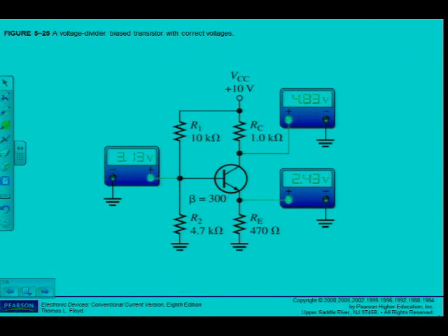All right, now as soon as you've calculated these values and you go and measure these values on the circuit that you've built or the circuit that you want to do troubleshooting on, but say for instance you built this biasing circuit like here in figure 5.25, and say for instance it works. How do I know it works? I have to go and measure the voltages and compare them with my calculated values. And how are they going to compare to my calculated values?